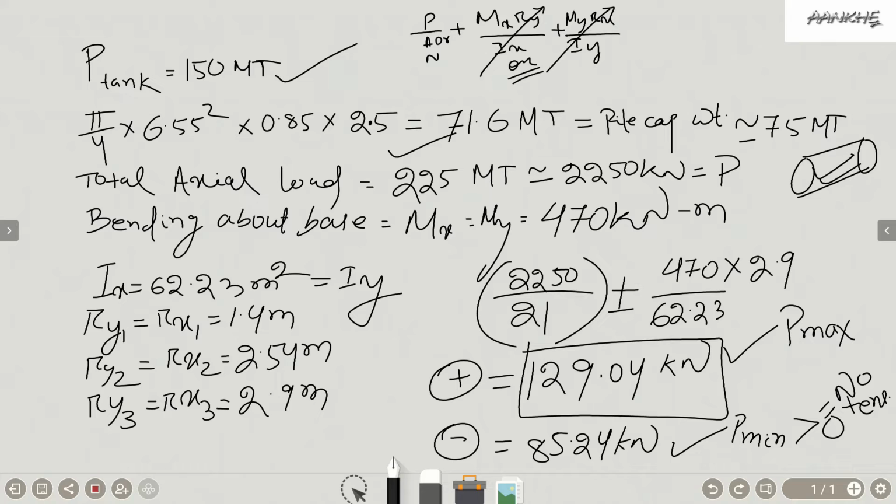It is obviously taken care of by the pile itself. Many people assume that it is included in the factor of safety or something like that, so we will not be taking the pile load. But again, after all these permutations and combinations are completed, I would like to add that we should take the self weight of the pile. So what is the self weight of pile?